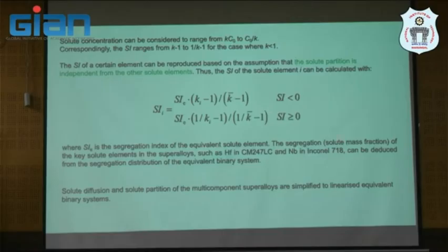And then we identify the segregation profile specifically for CM247 based on our understanding from the experiment: hafnium is segregated at the grain boundary, and niobium for the Laves phase, which is decorated at the grain boundary as well. So we focus on these two, but there is some other reason why we focus on these two profiles from a metallurgy point of view, which I will cover later.